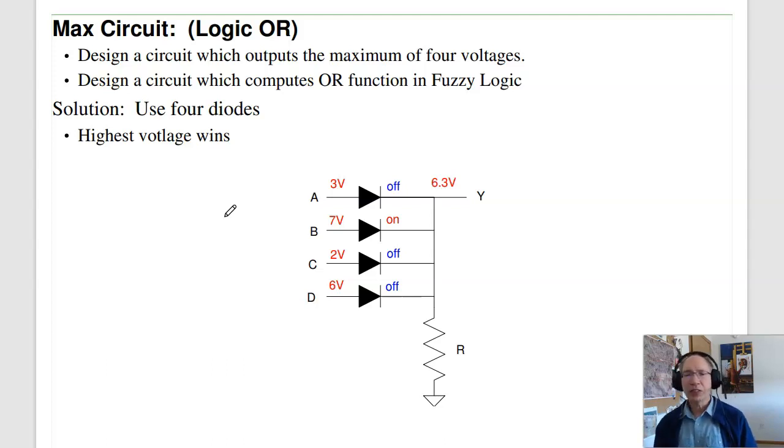Now let's look at the hardware. Come up with a hardware circuit to implement a max function or min function, and we'll also look at the average. So a max function is actually a diode circuit. If I have a bunch of diodes in parallel, this will pull off the maximum. Some people like to memorize that if the diodes face right, it's the maximum, face left, it's the minimum. I don't like doing that, partly because my memory's not that good, but also, as you redraw the circuit, it gets confusing.